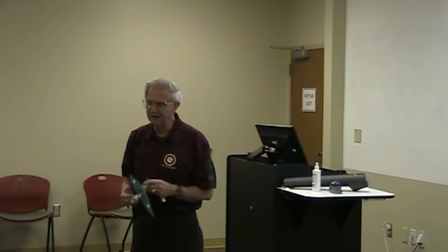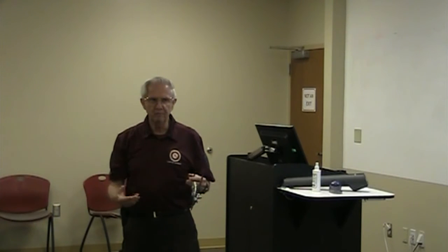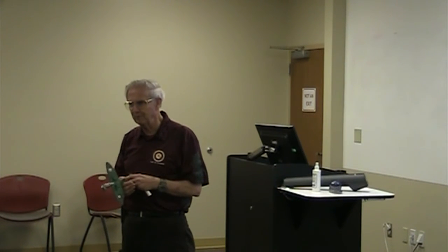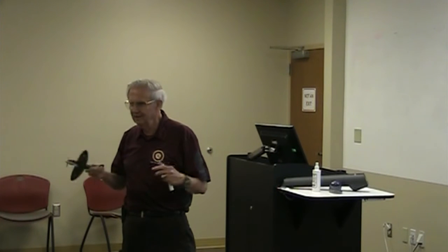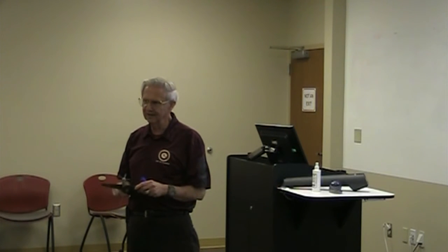So be careful is one of the things I'm trying to get across to you here: be careful about mathematically modeling, particularly this stuff, at anything beyond a few degrees of side slip. You're just fooling yourself that the answer you're getting makes sense. So with that said, I think we'll be in the flight test business a long time.